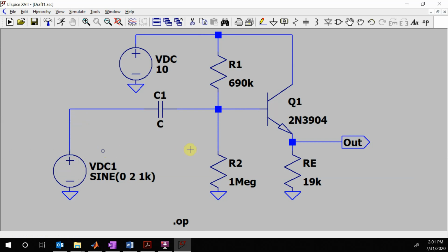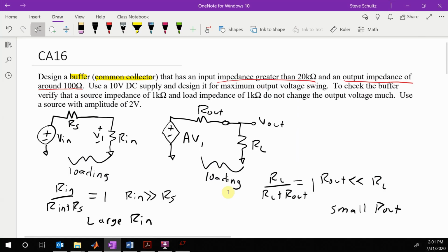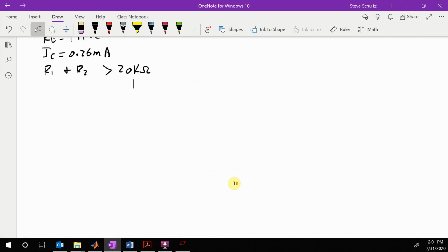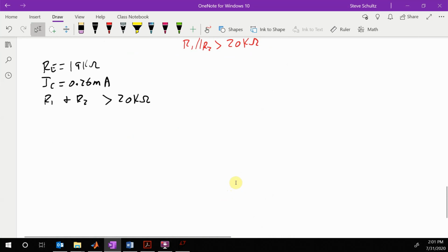Okay, so what value do we want this capacitor to be? If we're doing 1 kilohertz, we want to set this at like 100 hertz or 10 hertz even. So let's come in here, and we remember that my cutoff frequency is 1 over 2 pi RC, which is equal to, let's just set it at 10 hertz. We got lots of room. Okay, so what is my resistance?